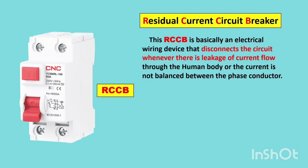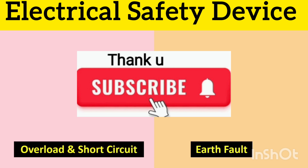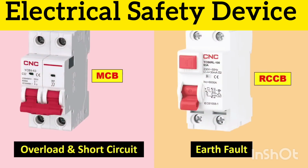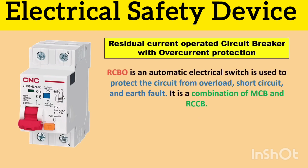Now if we want protection from earth fault, overload and short circuit, then we have to use MCB and RCCB, both these devices. But if you don't want to use two different devices, instead by using only one device you will get all the three protection. Then in this condition, you have to buy a RCBO. So through RCBO, you will get overload, short circuit and earth fault protection.